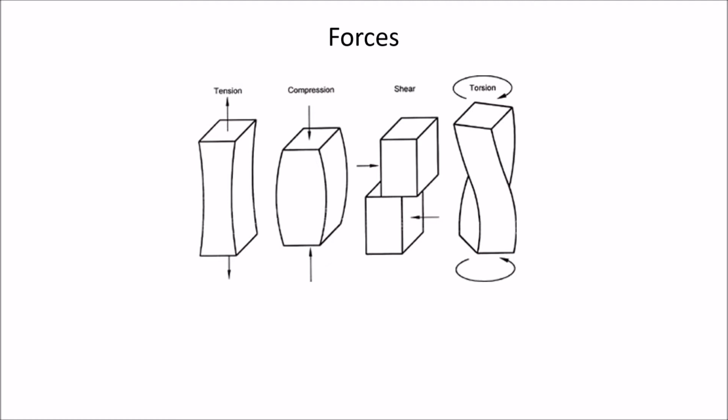There are four common types of forces. That force might be tensile force, or when the piece of material is put in tension. That's a fancy way of saying when the material is pulled apart from one end and pulled in the other direction from the other. So it's in tension and it's being pulled. One of those forces might be compression. That means when the material is being squeezed together, pushed together from opposite ends.